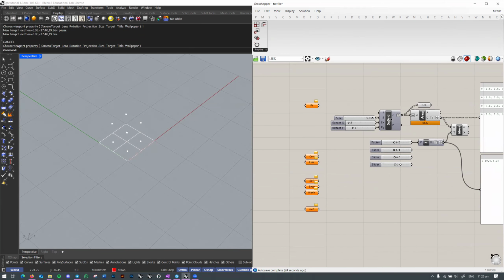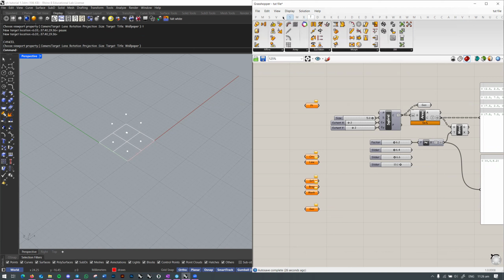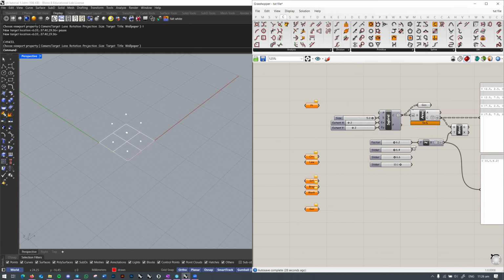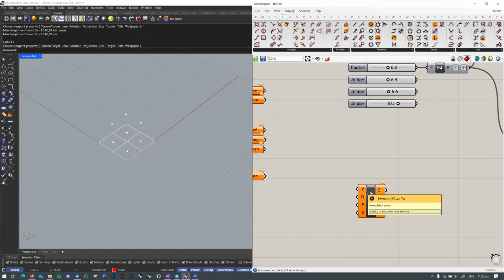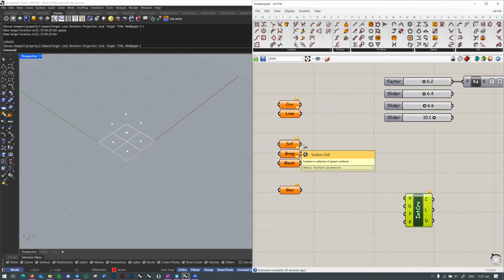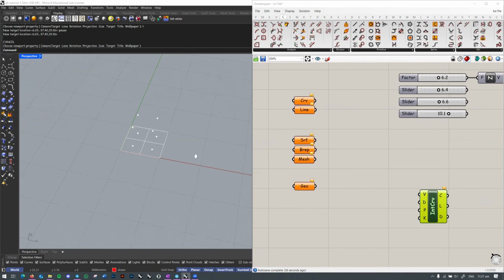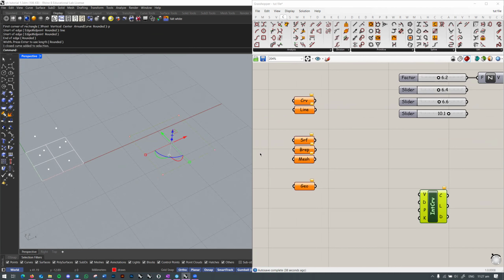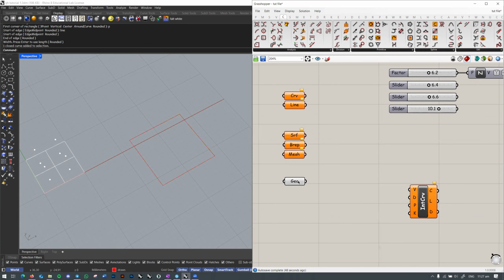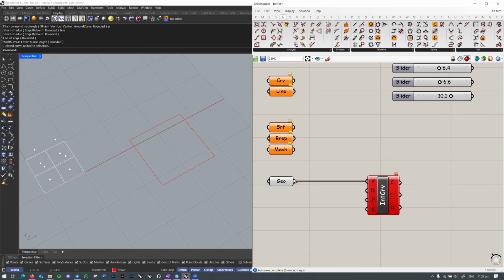Where if, for example, I create a component, say I want to interpolate. If it's asking for vertices, I cannot give it a surface to interpolate into a curve. I can't even give it a rectangle. Let's say I want to interpolate a curve around these points of the rectangle. I can't just throw this in here and expect it to interpolate. It's going to return an error because what it's asking for are points. It's not asking for a reference polyline instead.